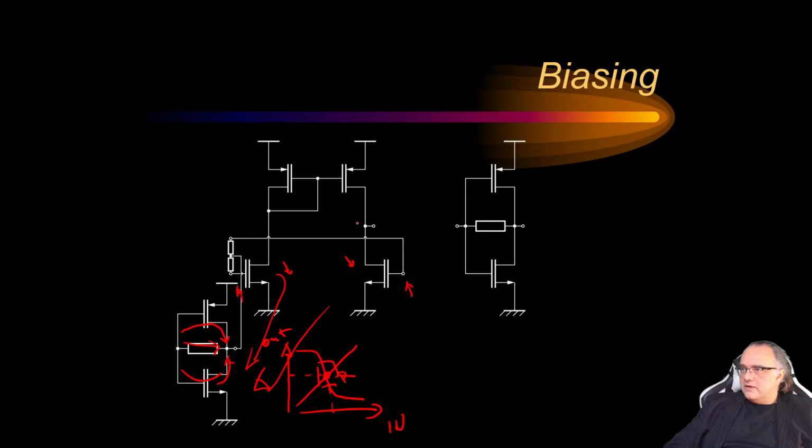So then we have here an output voltage, but this does not mean that it's optimal for the second stage. So this is why we'll decouple it for DC from the first stage, and we'll use self-biasing to generate on bias. So the self-biasing principle is like this, and this guarantees that this structure, the second stage structure, operates also at an almost optimal point.